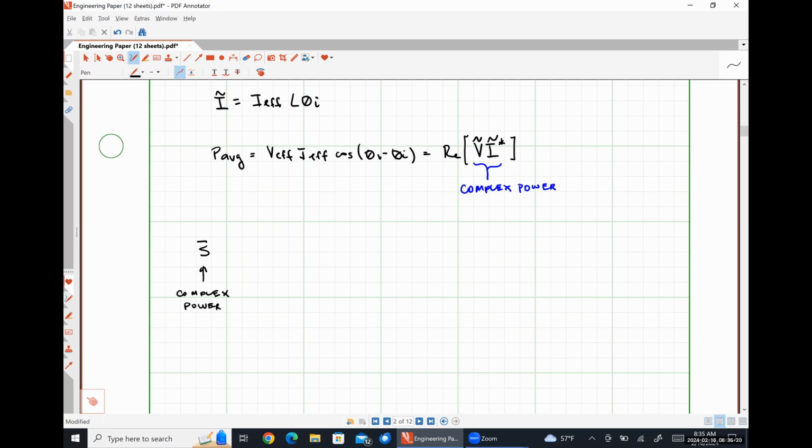is our complex power. Before we move along from this point, let's talk about units. This is 100% a trick question. What should the units of complex power be? It looks like it should be watts, but it isn't. And it isn't because electrical engineers just made up a unit so that we can tell the difference between complex power and average power, which is measured in watts.